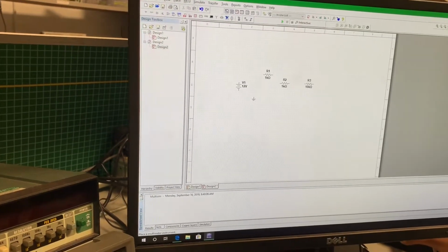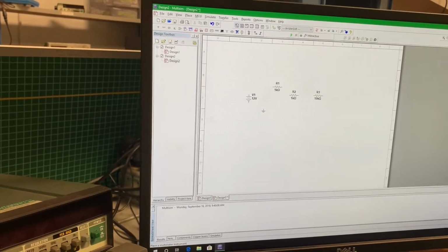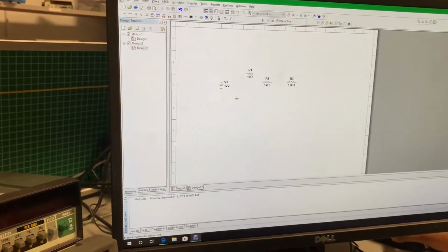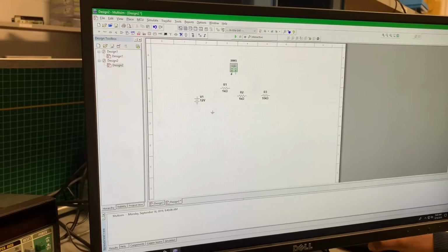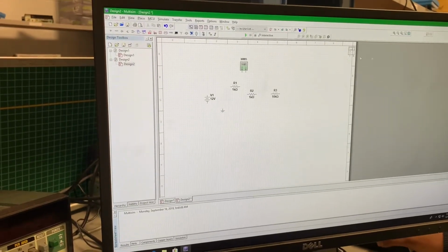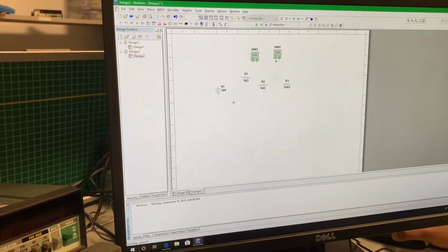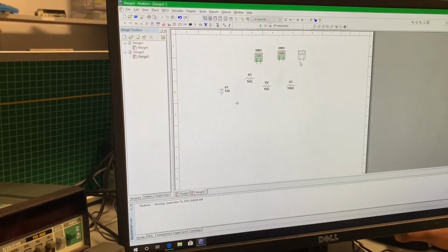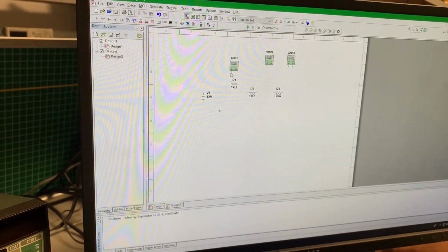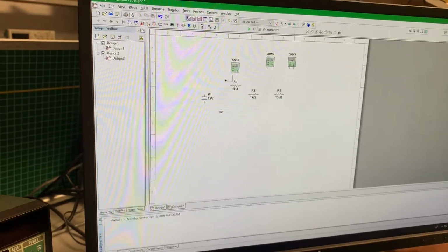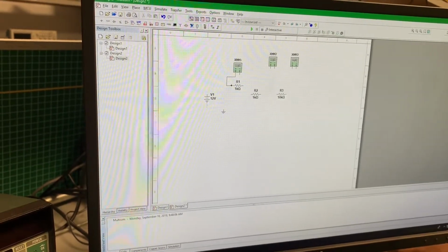But to get the resistors in the direction you want, we'll also pull up the multimeter from the far right, and this we'll use to measure the current, voltage, and the total resistance. So we have 3 multimeters, 3 resistors. We're going to start by checking the resistance to see that it's what we expect it to be.